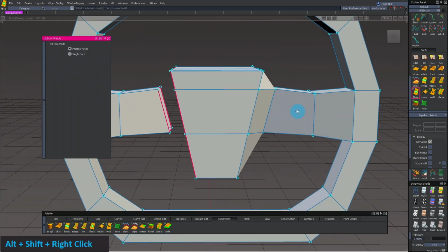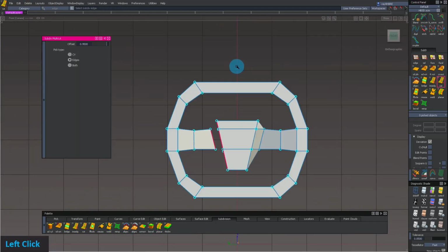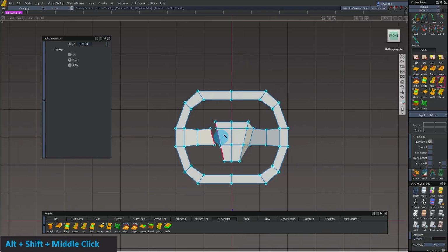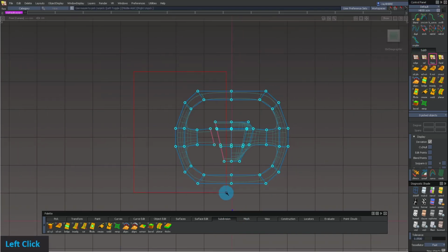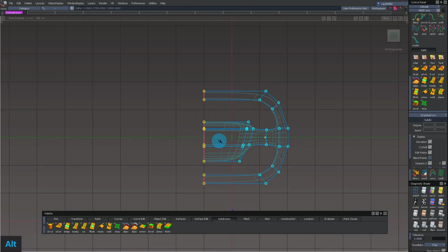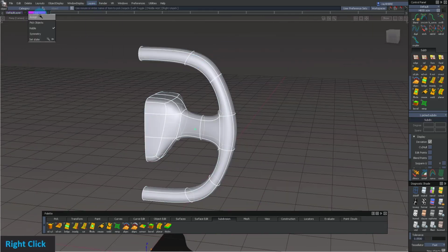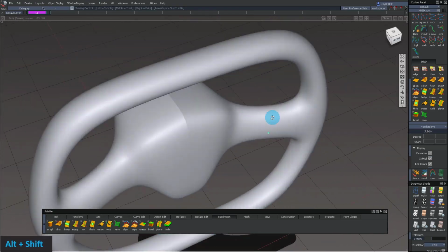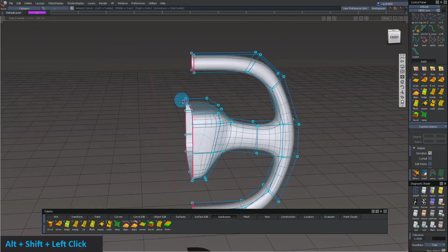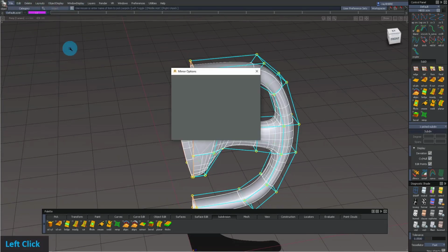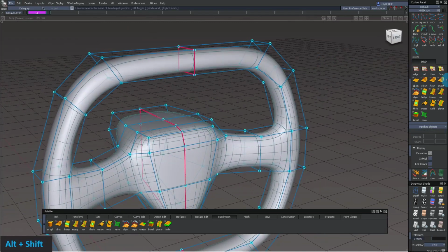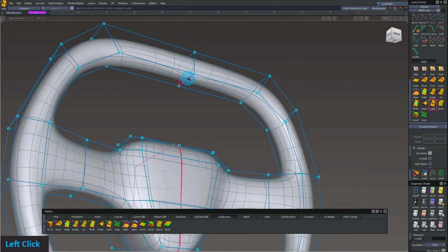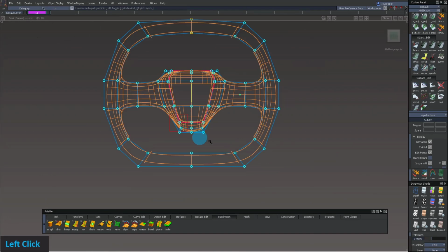If you notice, we actually lost symmetry. To get it back, I need to make sure it's equal on both sides. So first I'm going to cut it down the middle, and then delete one side of the model. A lot of times the symmetry tool kind of messes up, so a lot of people will just model the whole thing using a layer and then with symmetry. The only problem with that is that you'll get a little bit of a widow's peak, but towards the end of the project, you'll just merge them all together, right? You duplicate it from one side to the other, then use your weld tool, click on all of those red edges, and then you'll have a nice symmetrical model. And when you apply the symmetry tool again, you'll be able to model it.